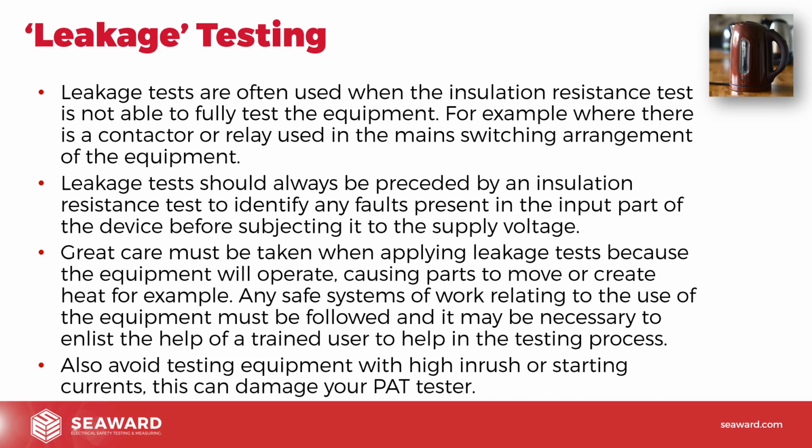Also, another thing we've got to look at here, it says also avoid testing equipment with high inrush currents or starting currents. This can damage your PAT tester. Yep, you've always got to think about this, because you're running the test through your PAT tester. Whatever current your equipment draws is going through the relays inside the PAT tester. It's being switched by the PAT tester. So if you've got a piece of equipment, now that equipment might be 13 amp rated, but when you turn it on, it can draw a huge amount of current for a short period of time from the mains supply.